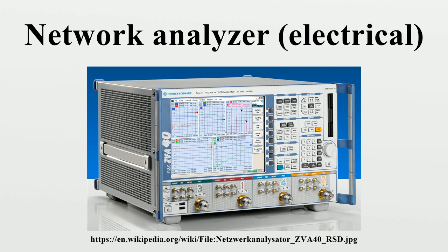Initially consider that SW1 is at position 1 so that the test signal is incident on the DUT at P1, which is appropriate for measuring S11 and S21. The test signal is fed by SW1 to the common port of splitter 1, with one arm feeding a reference receiver for P1 and the other connecting to P1 via the directional coupler DC1, PC1 and A1. The third port of DC1 couples off the power reflected from P1 via A1 and PC1, then feeding it to test receiver 1. Similarly, signals leaving P2 pass via A2, PC2 and DC2 to RxTEST2.